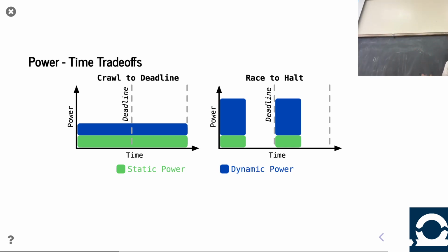And so you can kind of see how this trade-off boils down to this notion of what's your dynamic power versus static power. That's going to tell you the difference, right? Usually in hardware designs, to first order, you can say the static power is constant-ish when it's on. So static power is what you pay whenever you're on. So in other words, by turning fully off, you get to save the static power.